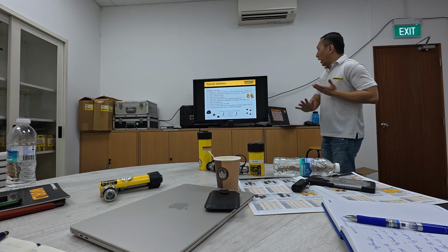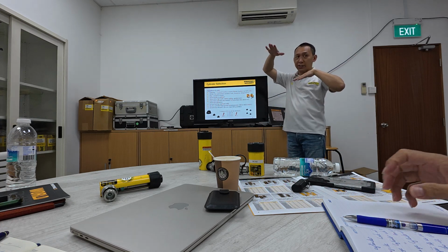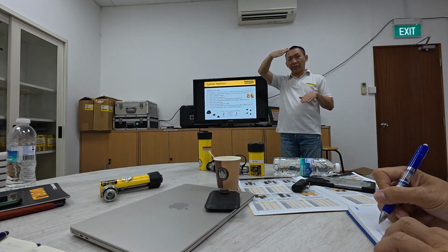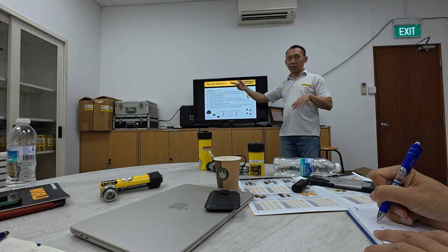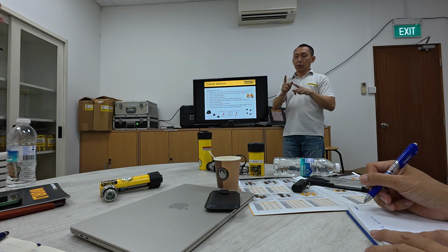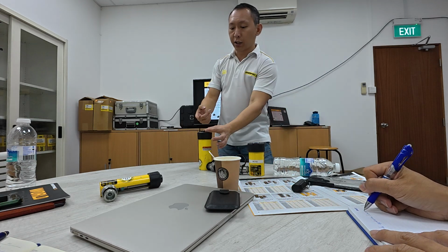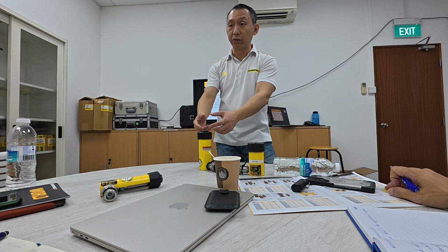Right? So in that application, what type of application? The surface, whether it's even, flat, or rough. Why so? Because if the surface is tilted, not rough, your cylinder, when you contact, will be side loaded. So that's why you have to advise the customer to buy a tilt saddle, so that it will tilt to a certain angle to contact with the load.